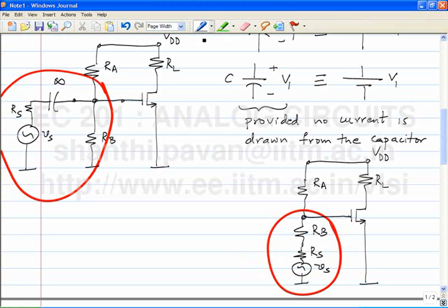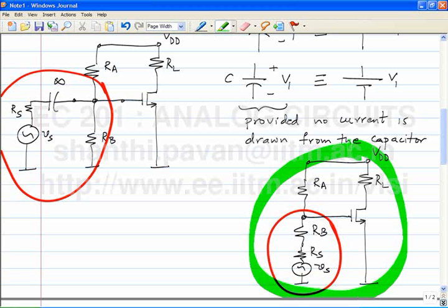That is a problem. What do you think is the gain from Vs to the output in that case in this chap? What is the incremental gain? Alright, so what is the incremental gain from Vs to the gate node here, this node? The question is, what is the incremental gain from Vs to that node X? In other words, if Vs wiggles a little bit, X obviously also wiggles a little bit. I want the ratio of this little bit to that little bit.